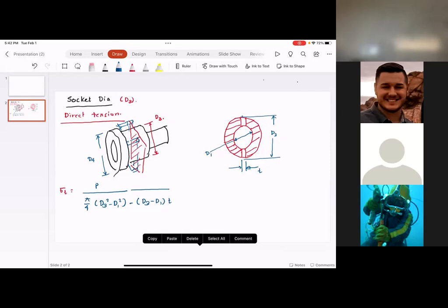What we are going to do is find out some basic dimensions of the quarter joint, look at the catalog items, and select a CAD model of that quarter joint. Import that CAD model inside SolidWorks or Autodesk, then apply finite element analysis, some sort of modeling techniques, find out the stresses, and make sure that the joint is safe.